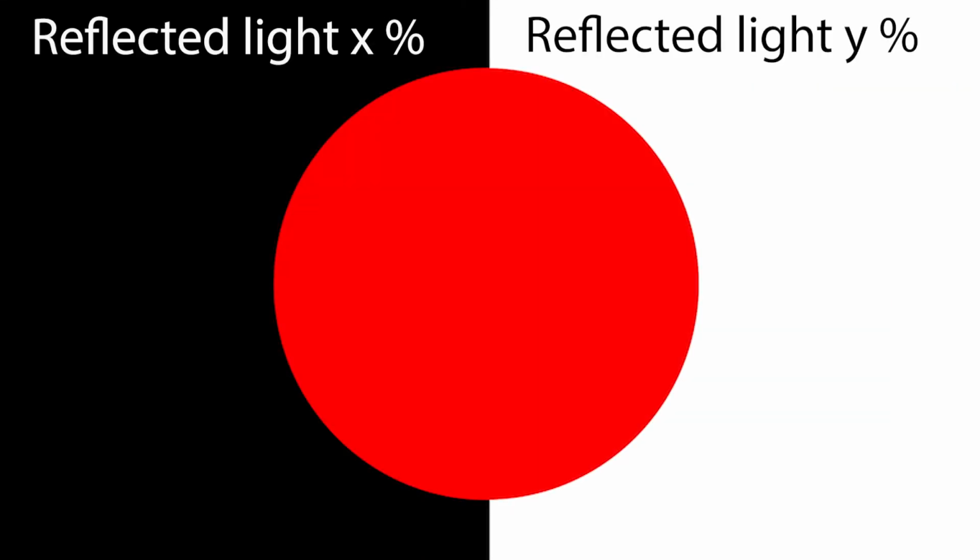Sometimes, the black color might not be 100% black and the white color might not be 100% white. This means that the average of the reflected light intensity between the black and white colors might not be 50%. Therefore, the motors will spin at different speeds than they should in the perfect situation. This problem can be fixed by using 2 light sensors.